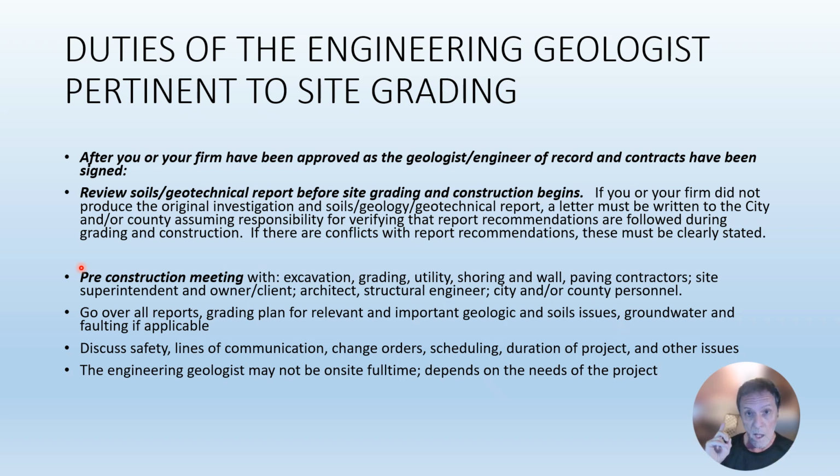I need to tell you, often, especially with small projects, you don't have pre-construction meetings. All of a sudden you get a call a day after or even the day of, hey, we're going to start grading this site. Do you want to come out to look at what we're doing? And we're going, yeah, where's the pre-construction meeting? Of course, by then it's too late because they've already got equipment on site. So you do your best to go in there and present pertinent information. Okay? Lines of communication are very important during grading of a project. Make sure everything's done right.